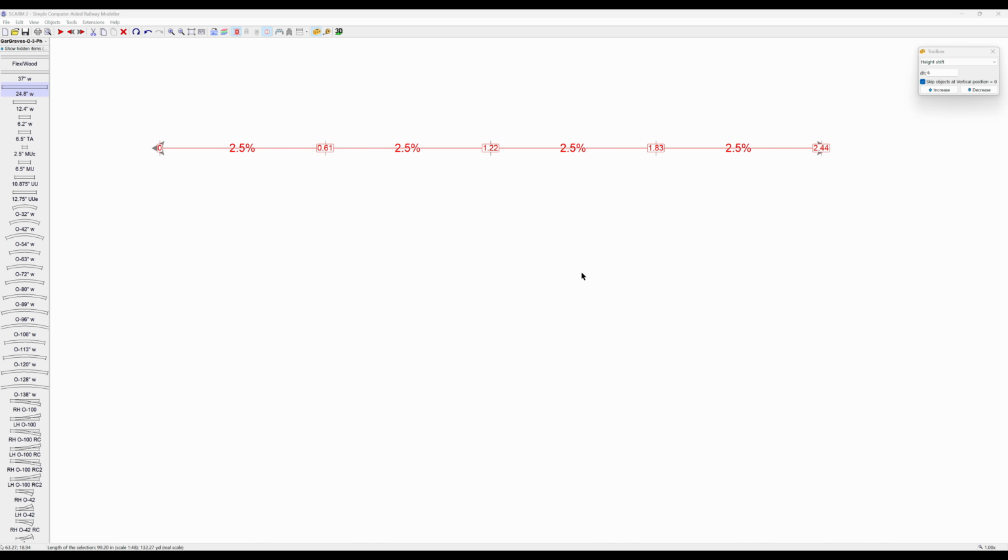Another feature of the height shift is you can zero out the selection set, and maybe you have scads of track with elevation, you just want to reset it, you want to start over. So set your shift value higher than the highest elevation.